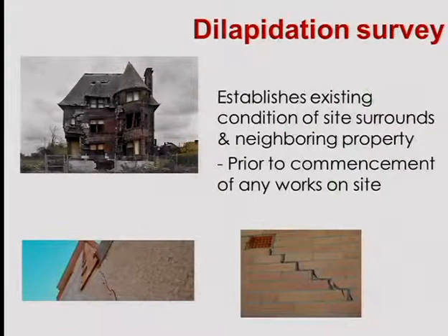When you start to build, before you make one step on the site to do any construction works, you need to do an investigation of surrounding structures. This is called a dilapidation survey. Now, why do you do that?